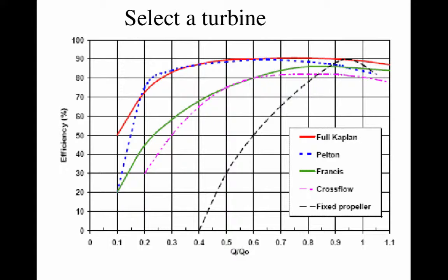That's pretty good, so we can follow the flow of this river quite well with one of these Kaplan turbines. And if we put in 2 of them, we could do even better. Even at 10% of its rated flow, or 260 cubic feet per second, it is still 50% efficient. So we can operate this turbine for quite a long time.